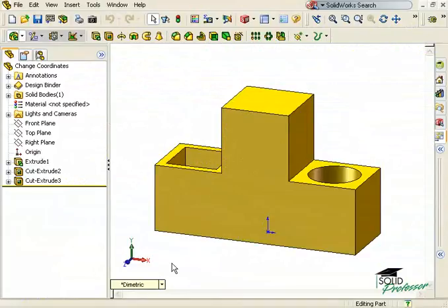Changing the orientation of a part relative to the global coordinate system can be a tedious process. Because of this, it's important to consider the reason for wanting to change the orientation. There are two common reasons. The most common is to redefine the standard front, top, and right views. This leads to more descriptive isometric views and helps in the creation of drawings.